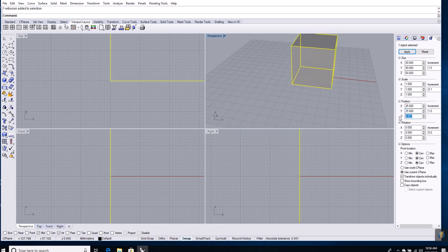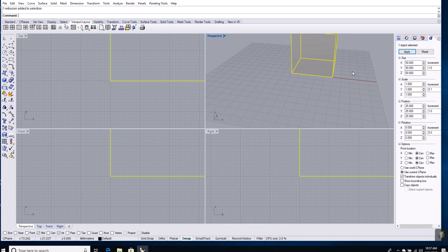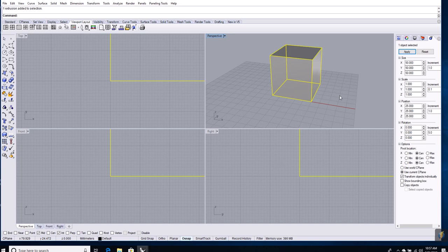If you're drawing things by freehand, it's fine to draw freehand to create the type of model or the type of solid geometry you're going to create, but then you want to size it using the box edit tool. And one thing that I would say you have to do as a best practice is, if the final output of your 3D print is 50 millimeters by 50 millimeters by 50 millimeters, it means that you design it from the very beginning at the exact scale that you're going to output it.